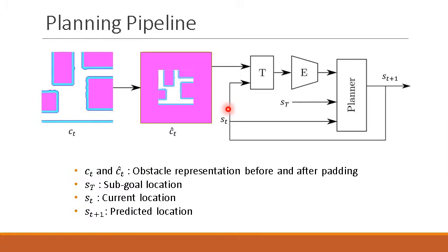The network starts planning using the current position, the target position from the global plan, and the local cost map to generate a sequence of kinematically feasible states. For each step, if the predicted state is kinematically feasible and is collision-free, it is used as the current position for the next prediction. Thus, for each feasible point, an egocentric cost map encoding is required. This cost map is achieved by translating the initial cost map. It is necessary to pad the obstacle map such that no loss in obstacle information occurs after transforming the map